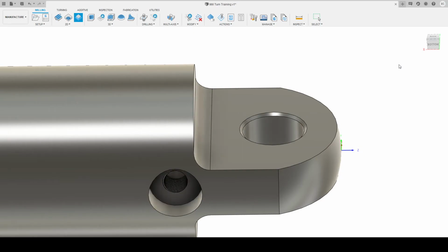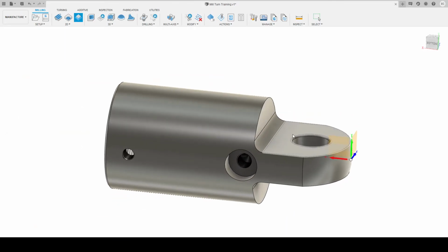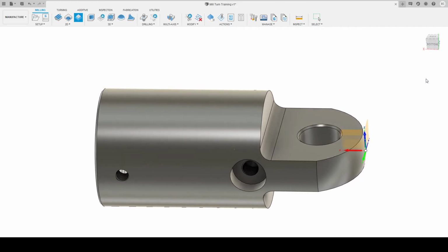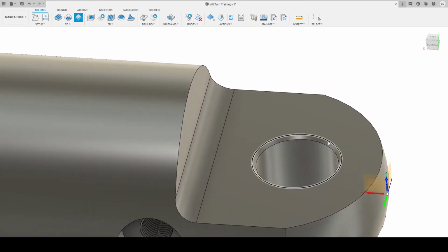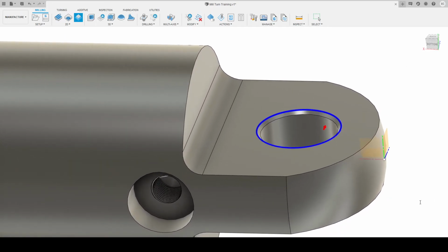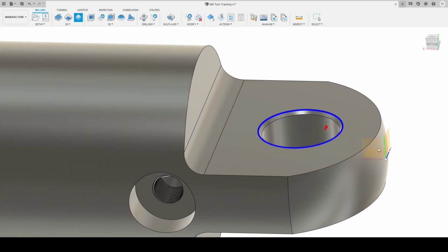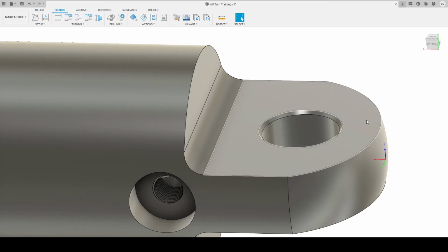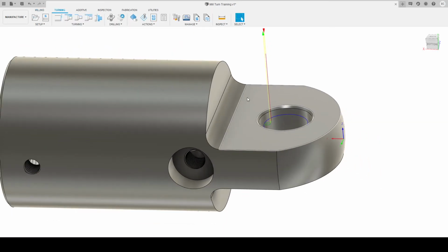We'll go to the geometry tab. We'll select tool orientation. We want to orientate it this way, so Z's pointing up. And then our contour that we want to machine is this one. We jump into our passes tab, and because we already have a chamfer modeled, you don't need to put a width in. All we simply do is offset the tip down. So we click OK. Beautiful.